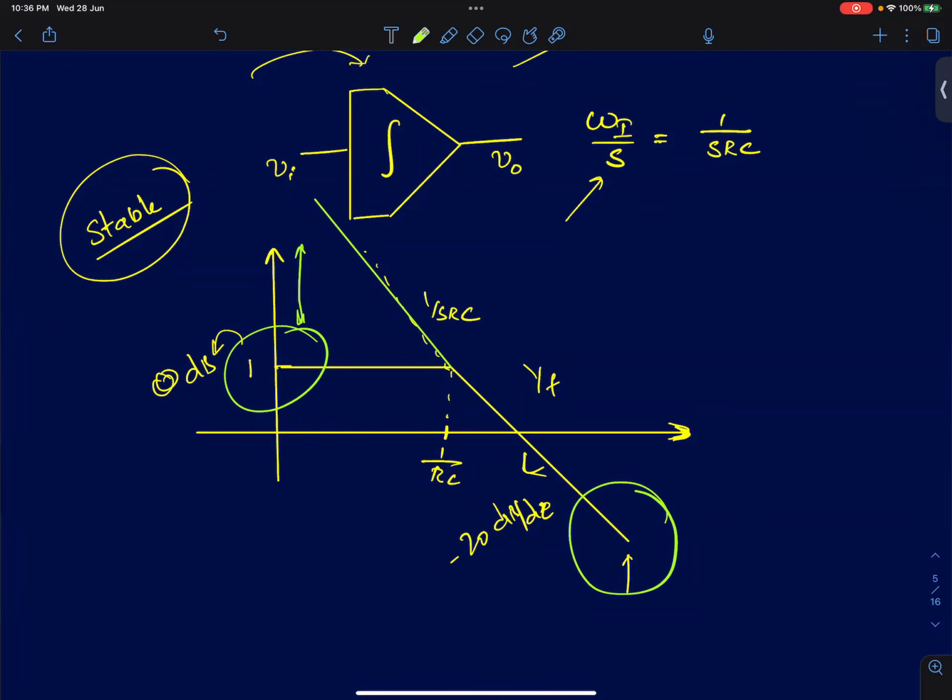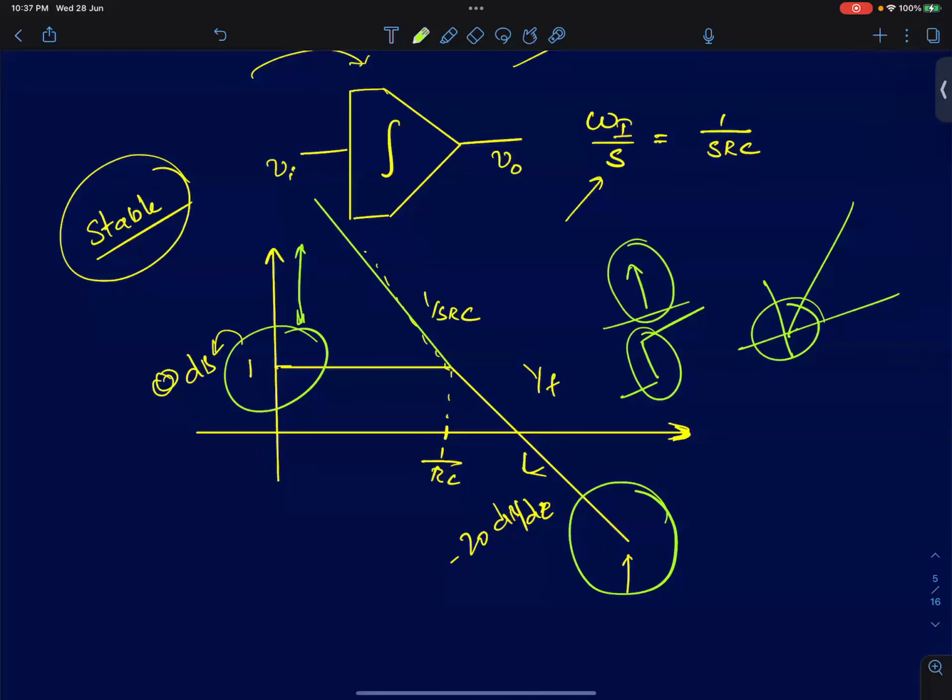Now, just to quickly refresh your memory, if you are to plot the response of a system, generally what we will be interested in is the transient response. You suddenly excite the system: you feed an impulse, or a step input, or even a ramp input. At the origin, all these three functions have discontinuities, which means there is a sudden change. An impulse is a huge change at the origin. A step input is a finite change, but it's still a sudden change.